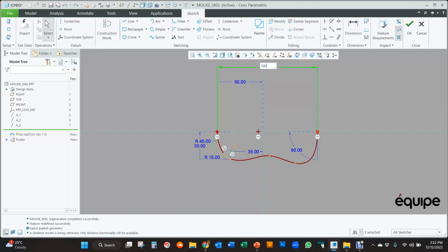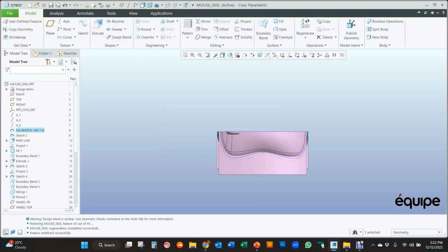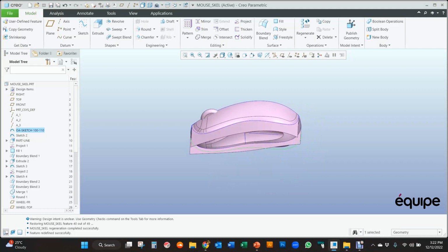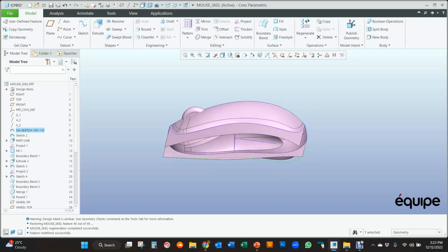Marketing said it's too long, so we want to turn that down to 100 and make the whole unit shorter. And this can also be done if you're doing different sizes. You have one at 110, copy a new sub-assembly across, do a backup with all your parts, and create a smaller part, but still keeping the same look and feel.